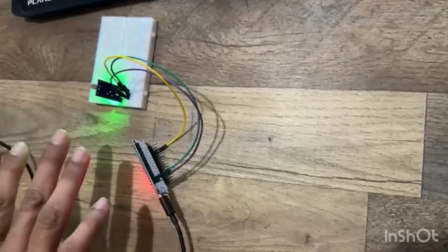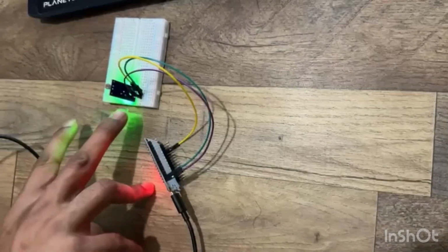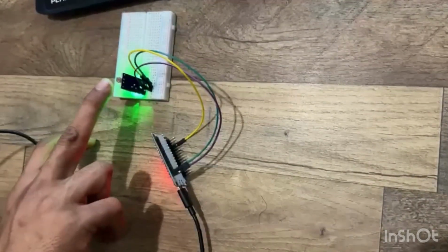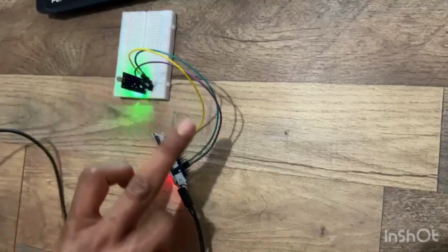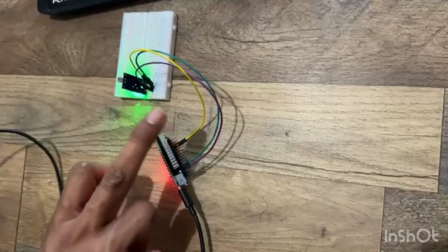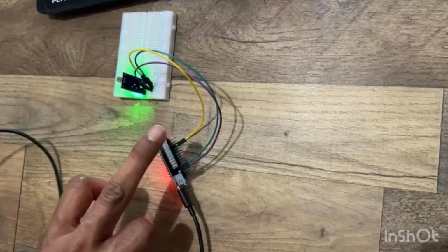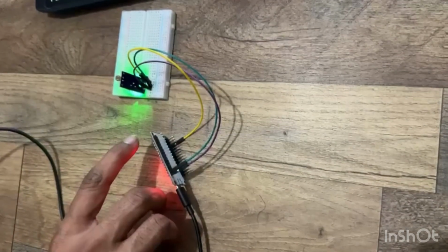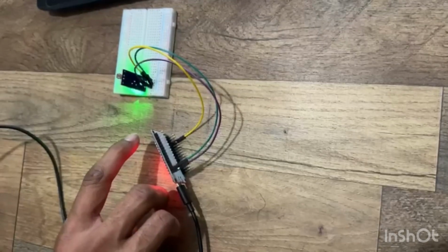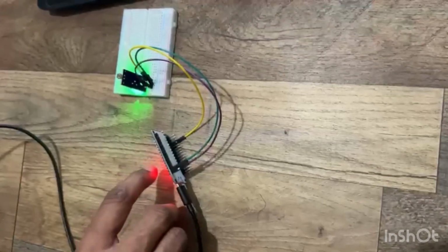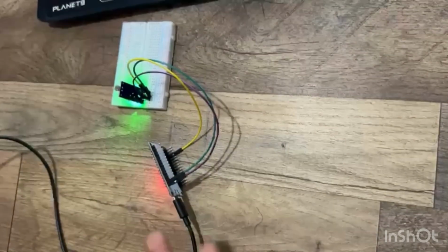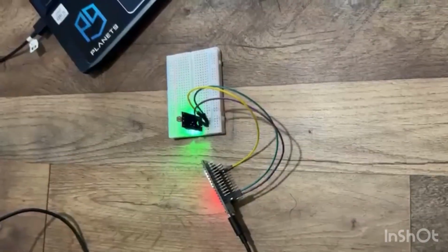So we're gonna discuss how this system works. The LDR sensor detects the light and it sends the signal to the ESP32. The ESP32 reads the signal and converts it into digital light intensity values using the ADC, which is the analog to digital converter. These values are then published using the MQTT protocol to a broker. Finally, we use Grafana to visualize the data in real time.